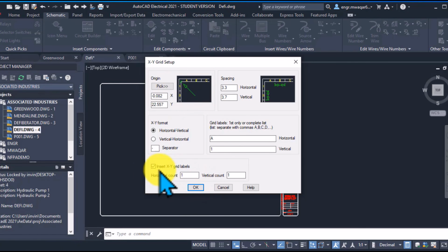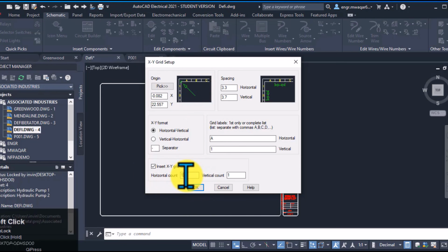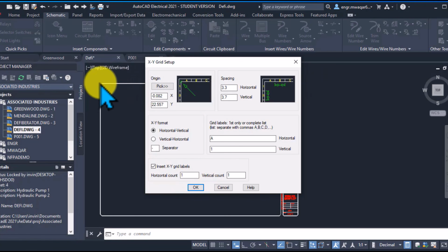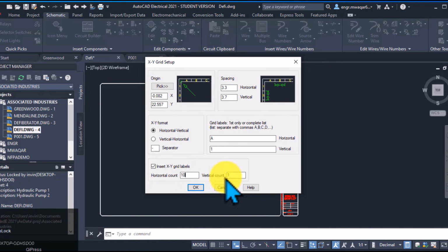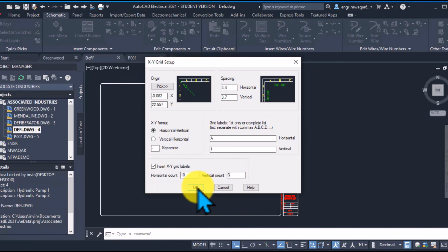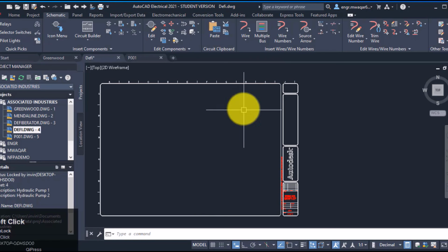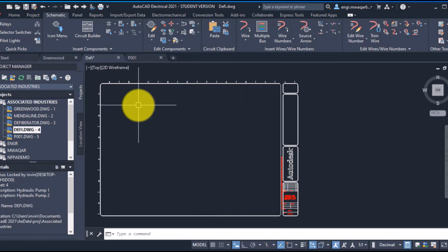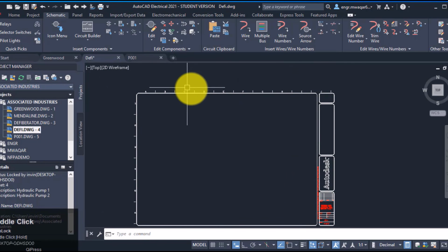Correct. And this system is incredibly common in European standards, the IEC standards, or in specific industries like automotive manufacturing. Why do they prefer it over ladders? Because their drawings tend to be extremely dense. They have massive, complex components that simply don't conform to a clean rail and run visual style. The grid allows for a much more flexible, almost free-form placement of components because you aren't tied to a specific run spacing. You just put it where it fits best on the grid.